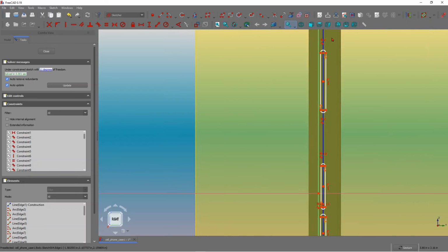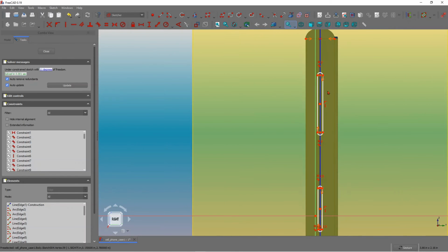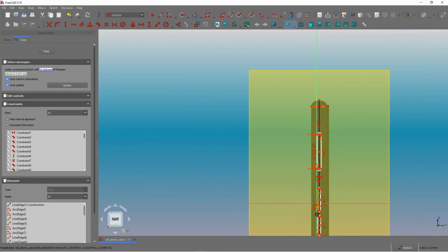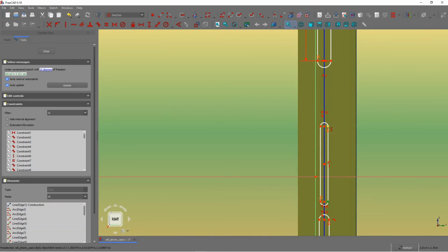At least we have some kind of a cartoon right now. So the next thing is to give some dimensions and constrain them. So let's see how much we want to give. Let's increase that a little bit, say 6.65 inch, and then we want to give these guys some dimensions as well. So 0.3, 0.42.